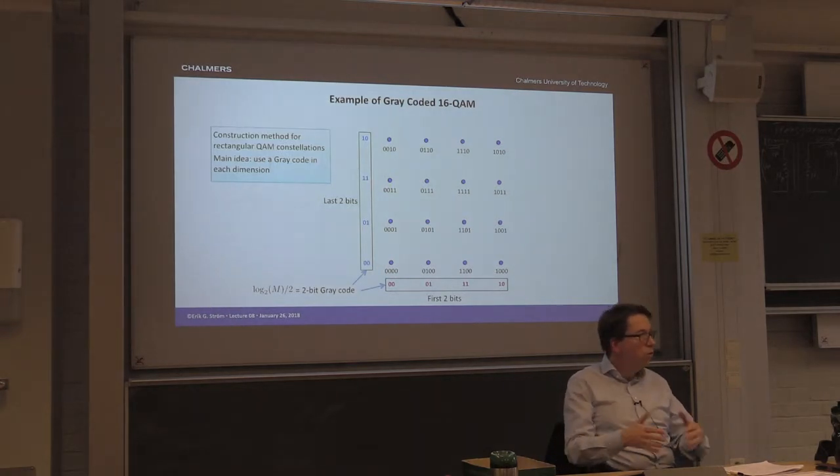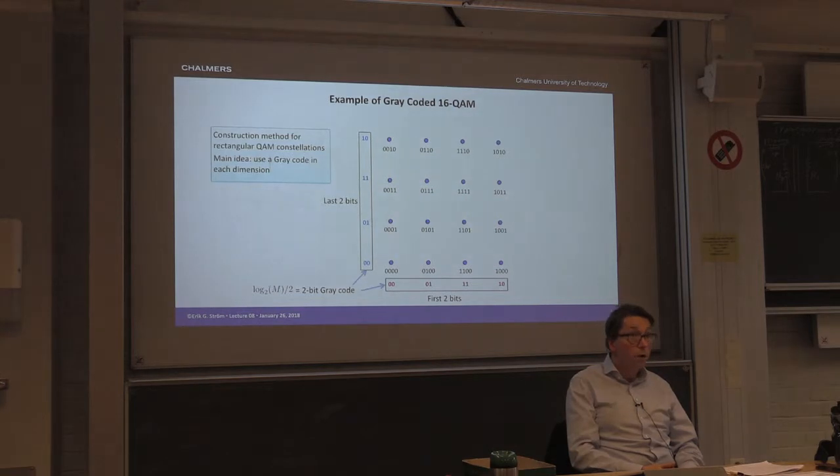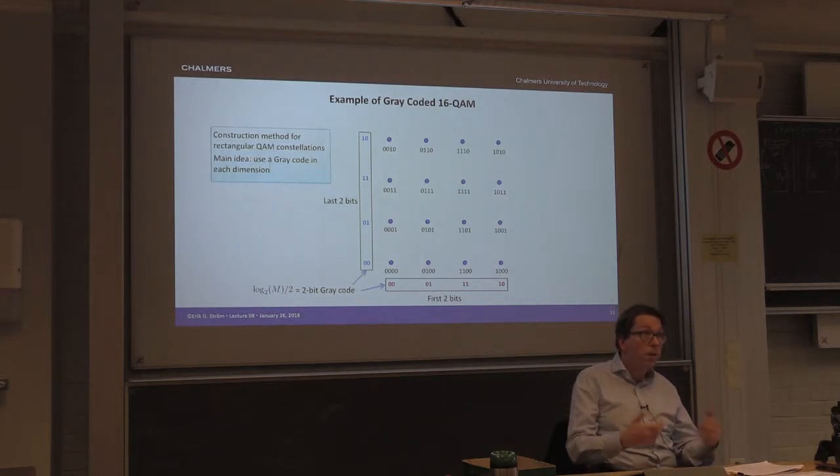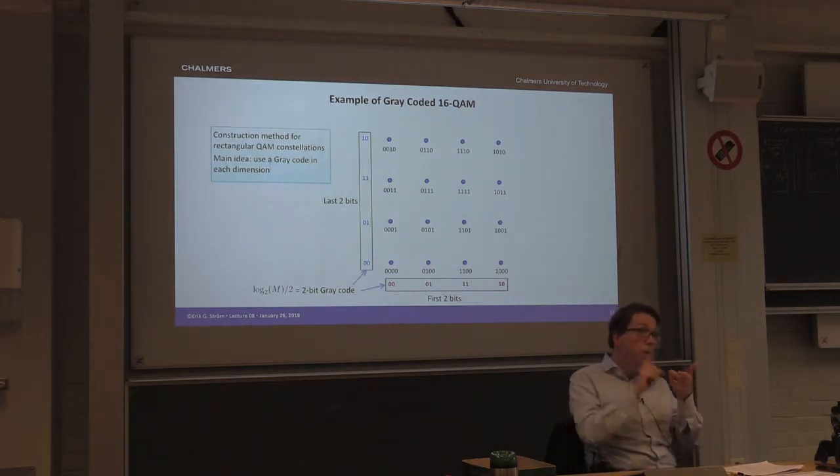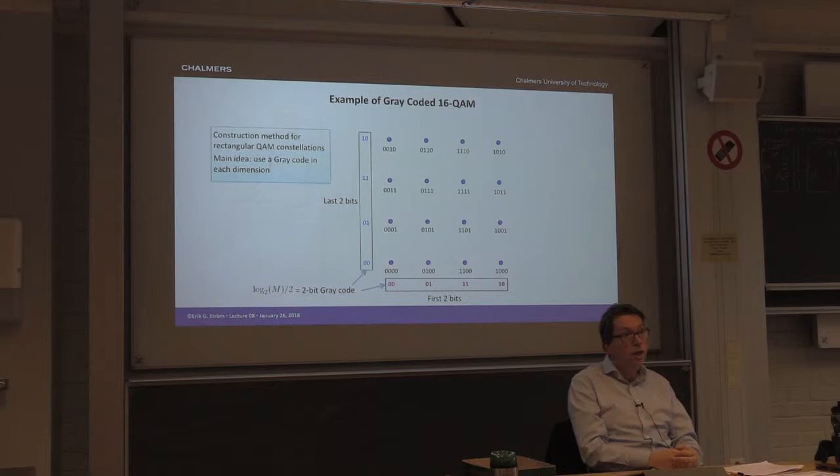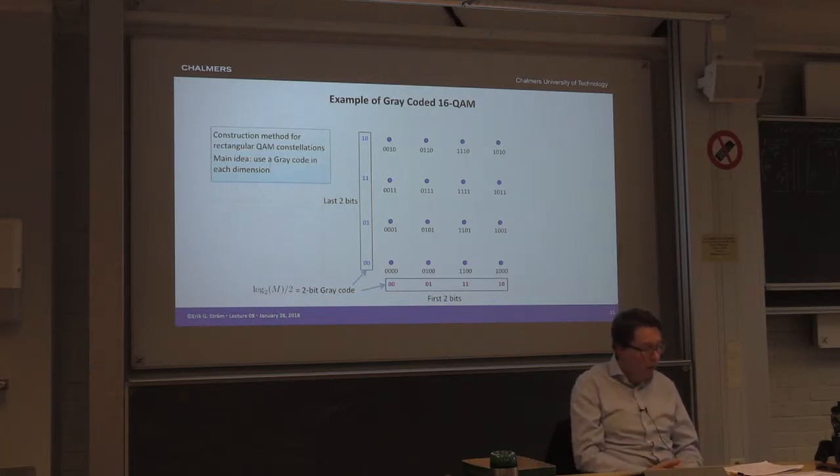And what we'd like to do is to minimize the number of bits that are in error. That's one thing that we would like to achieve. Then we also want to be power efficient and energy efficient at the same time. So getting down the symbol error probability and bit error probability is important. And we can do that by playing around with bandwidth and power.